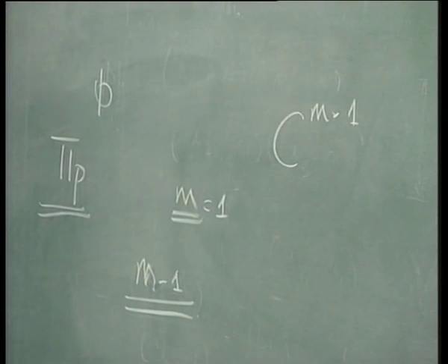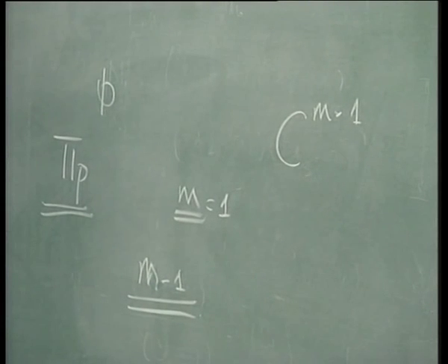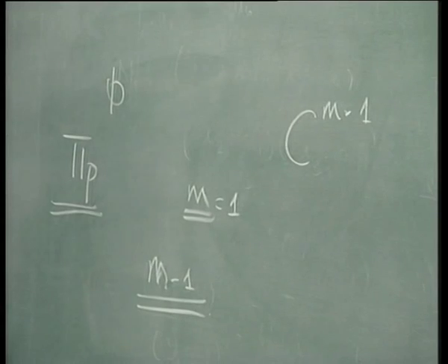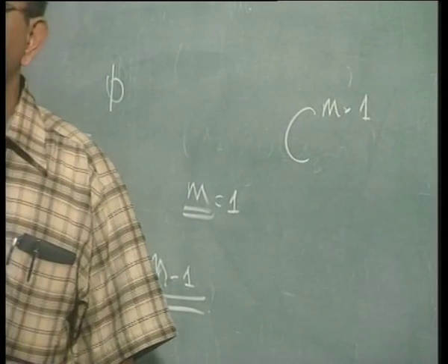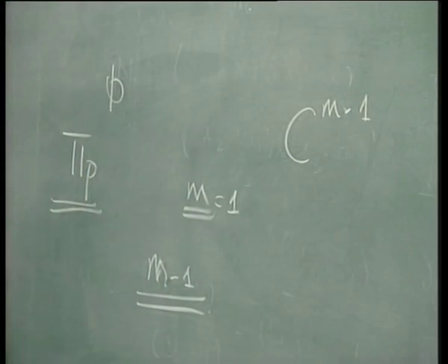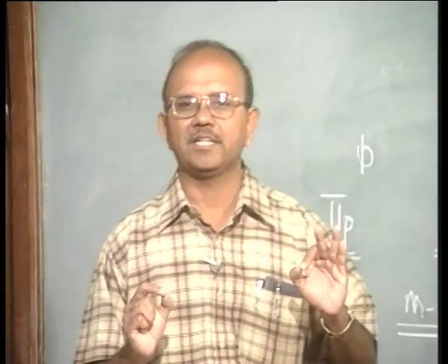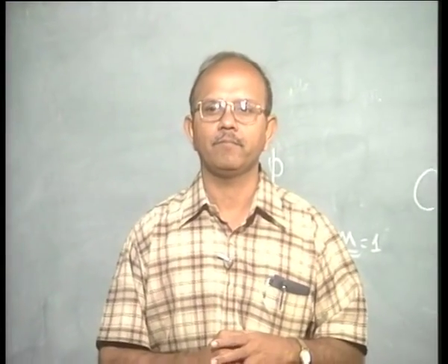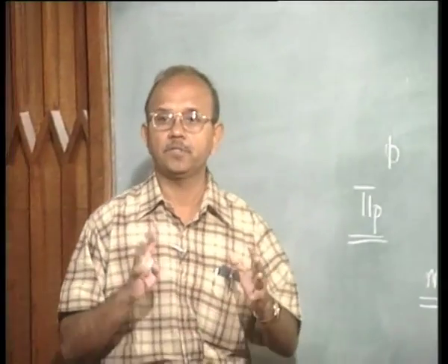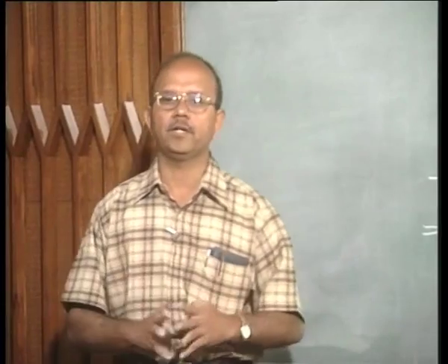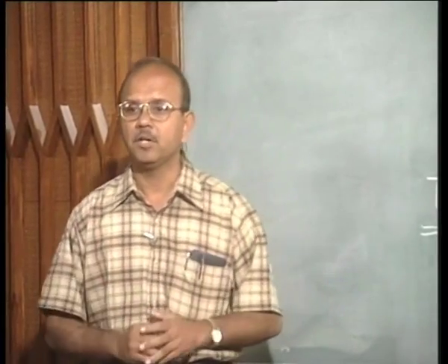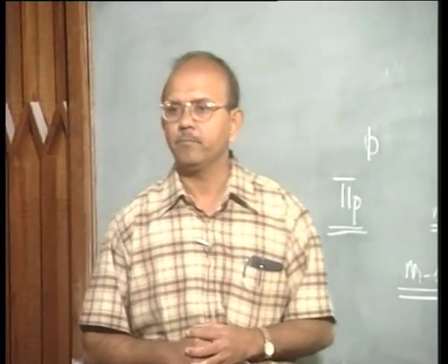If the slope happens to be continuous, which is the first differential, then what is the element I will be using? C1 elements. So when someone says I am using C0 elements, now you understand what it means. That is the second condition. I am just pointing out 4 important conditions that should be met by the interpolation function.